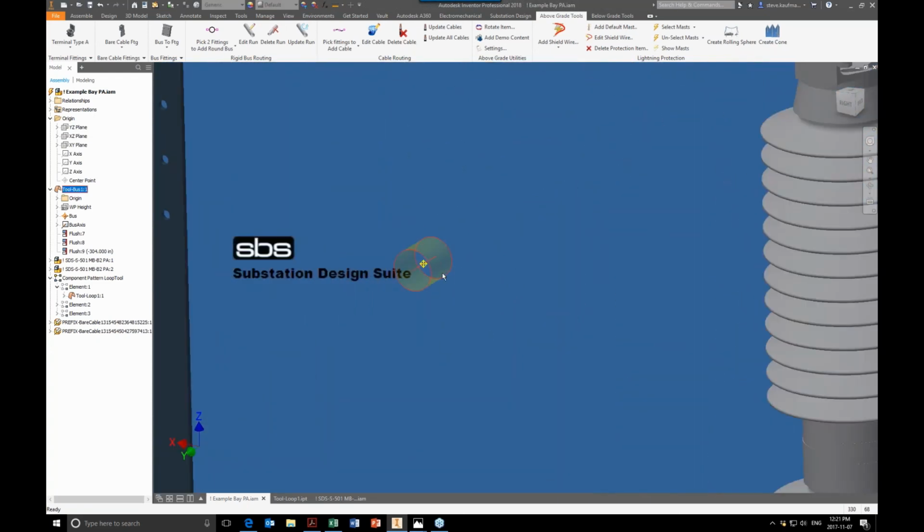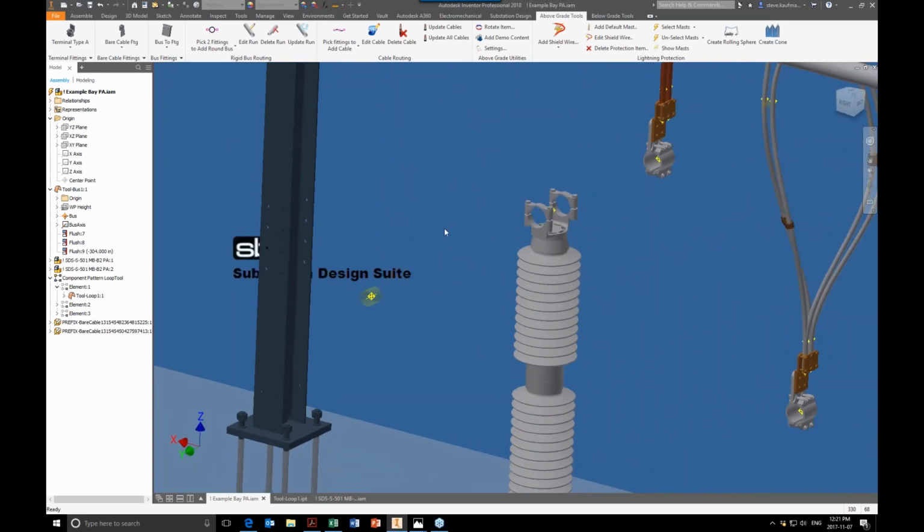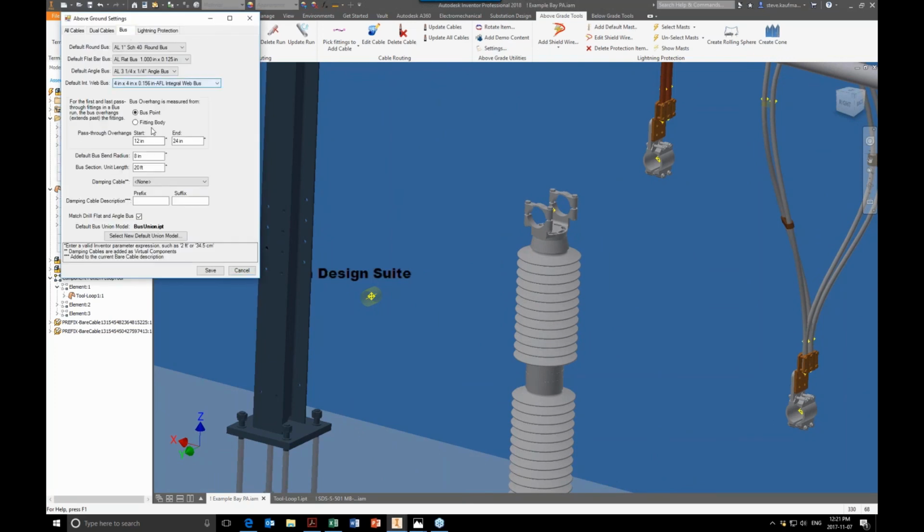What if I need to come up with some bus ends or something? I have no idea offhand, but I can do that. With the new 7.1, we have the bus tool that allows us to have different lengths on either end of the bus, but we may want further detail or information, or a point where we don't want to cross our dependencies from one island to another for constraints. You never want to have constrained parts in one island or subassembly to another subassembly. You don't want to constrain parts that way. So maybe this would help in certain situations.